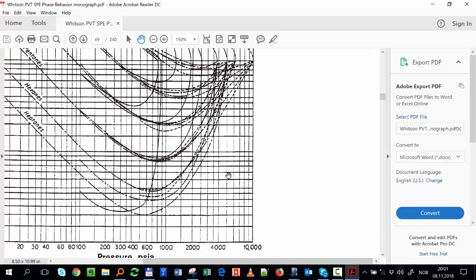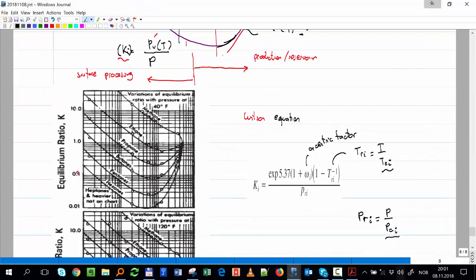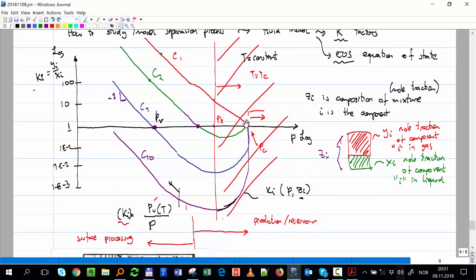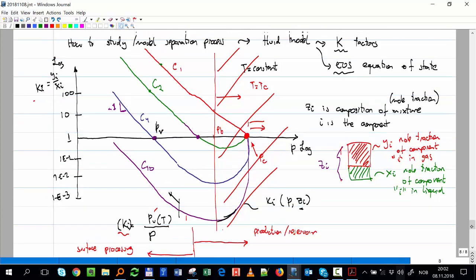In reality, you assume basically that the curves will all join at the critical point, but only for the critical temperature. For all other temperatures, they reach only up to the bubble point. But what I do is prolong the curve until they join, and I call that the convergence pressure. I use that as a tuning factor, but don't worry about it.